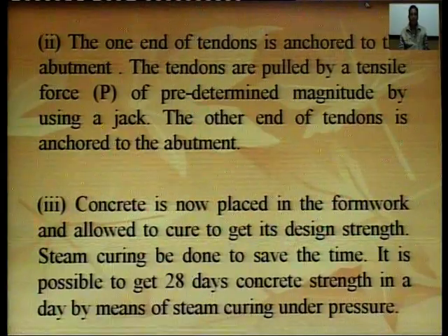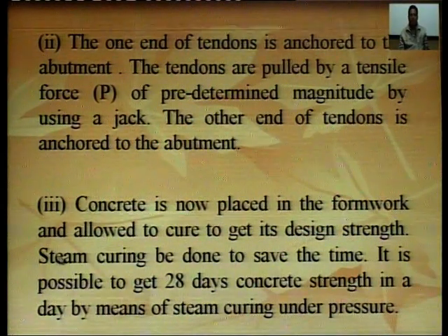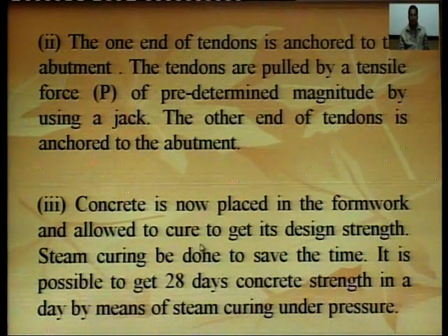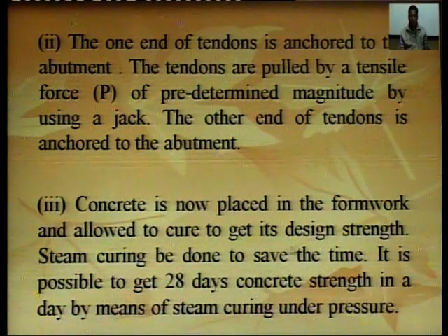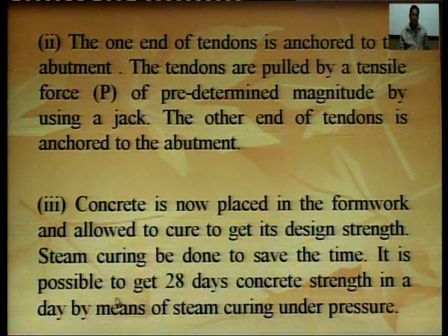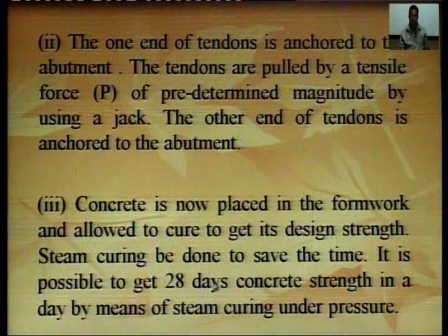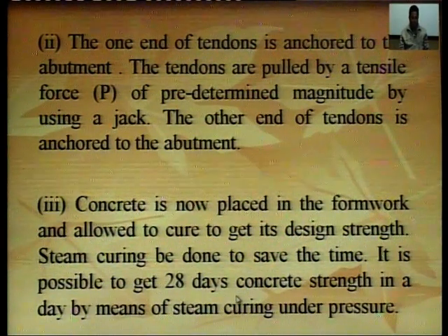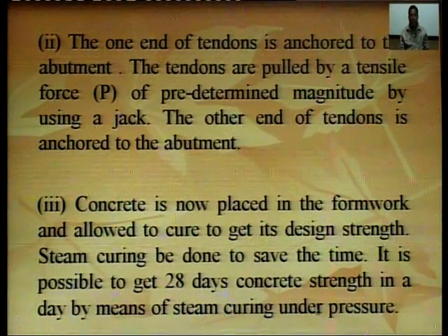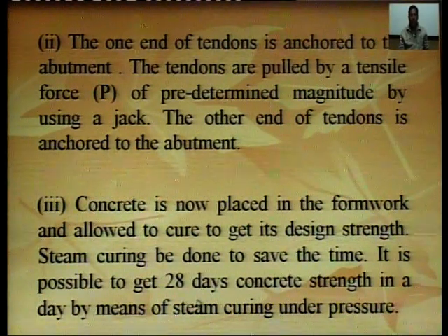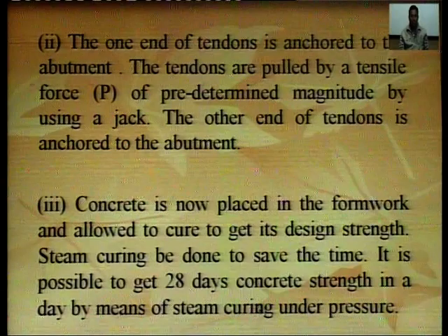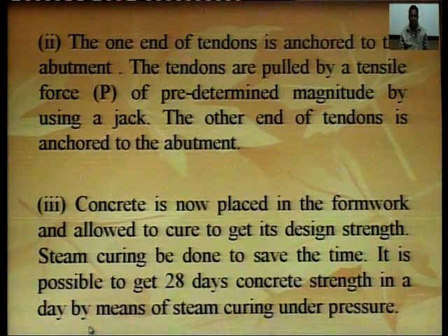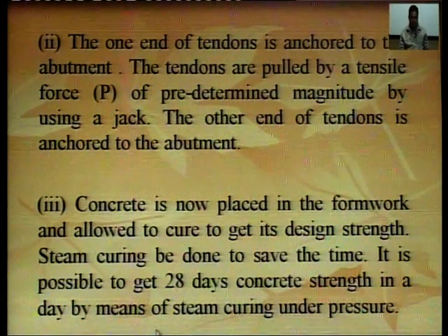Next, concrete is now placed in the formwork and allowed to cure to get its design strength. Steam curing is done to save time. It is possible to get 28-day concrete strength in a day by means of steam curing.